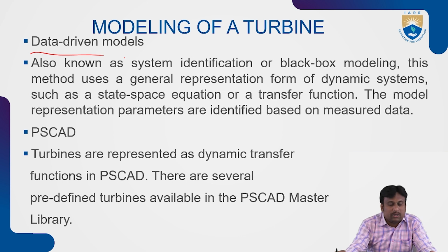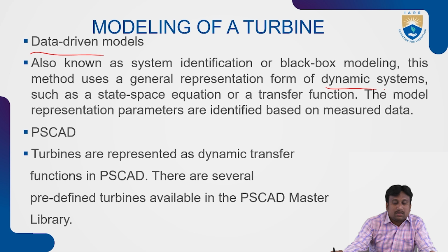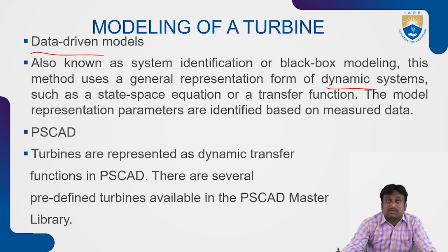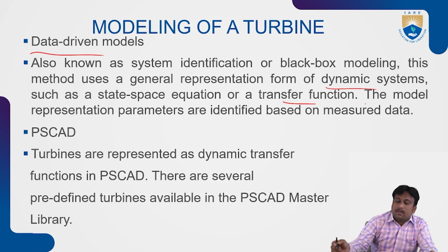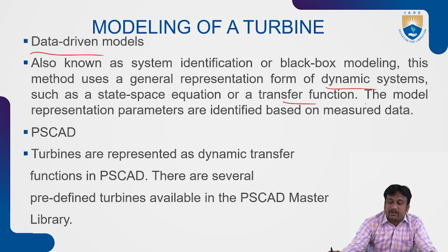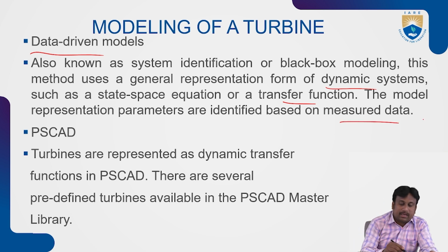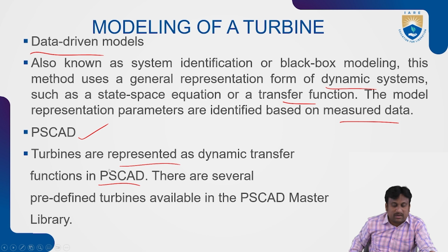Next are data driven models, also known as system identification or black box modeling. This method uses a general representation of the form of dynamic systems, like a state space equation or a transfer function. The model representation parameters are identified based on measured data, like in PSCAD. That means turbines are represented as dynamic transfer functions in PSCAD. There are several predefined turbines available in the PSCAD master library.